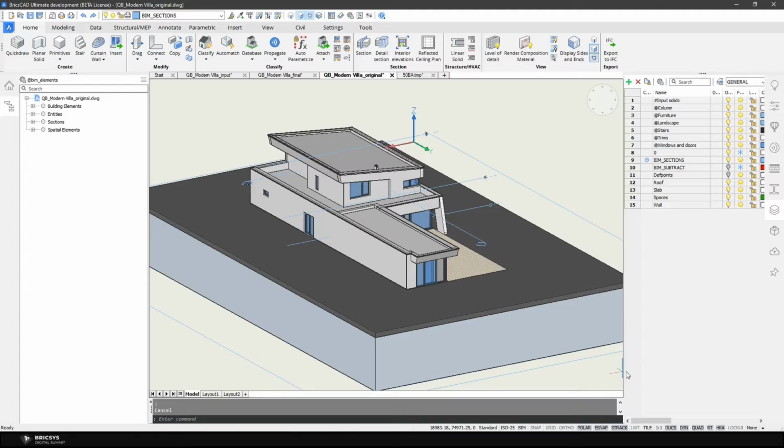How to get here is basically you need to use propagate or manually add some windows, and you can use auto match to add compositions, and the end result can be a BIM model ready to be quantified in terms of finding out how much building material you need to build this building, and to stick a price tag on the building construction elements.